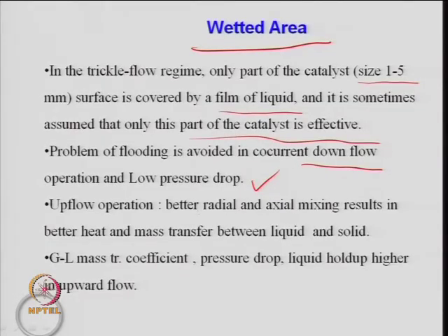If you have the upflow operation, this problem can be avoided. You will have better radial and axial mixing, the gradient will be less, and when this is less, your heat transfer and mass transfer rates between liquid and solid will be higher. So, this is the advantage. Another advantage is the gas-liquid mass transfer coefficient. The pressure drop and liquid holdup will be higher when you have upward flow. So, these are some advantages, but higher pressure drop is again an undesired property when you have an upflow operation. Both upflow and downflow have some advantages and disadvantages, but most of the time the trickle bed reactor operates under the downflow operation.